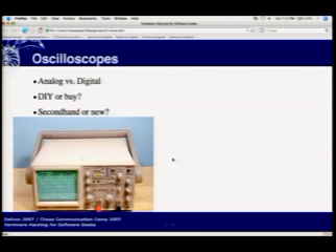How many people know what an oscilloscope does? Okay. It's basically a graphic plot of voltage over time. Most basic models will have usually 2 channels that they can display simultaneously. Analog ones look like this and have an actual cathode ray tube. Digital ones have usually an LCD screen and are usually a lot smaller, especially shallower. You can build your own oscilloscope, but chances are the bandwidth is not going to be fantastic. It'll probably be good for audio work, possibly for some TV work, but you'll start to lose it around RF, and it certainly won't do 100 megahertz buses on modern microprocessors.